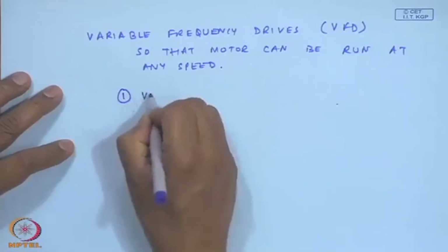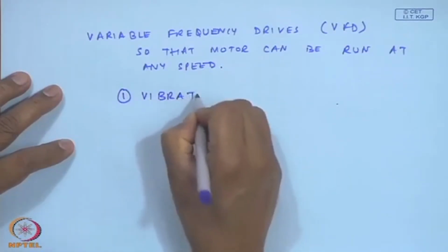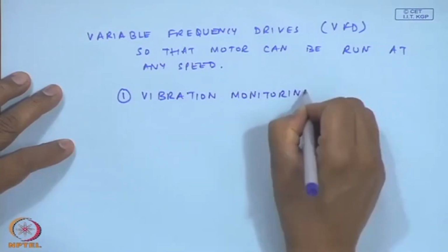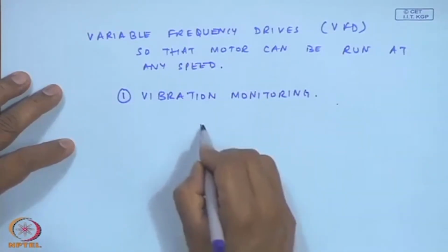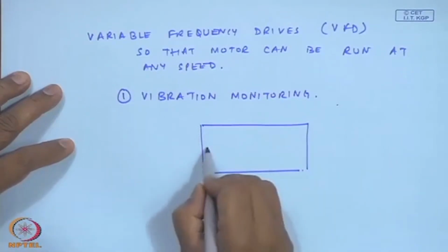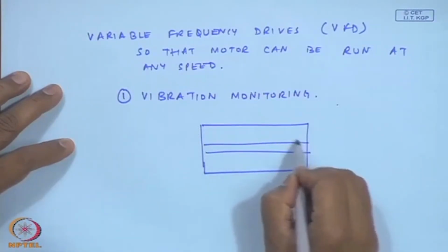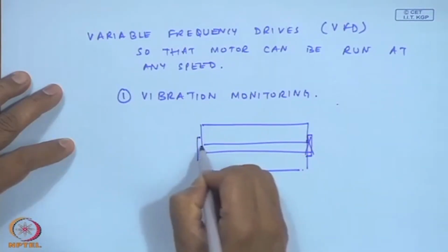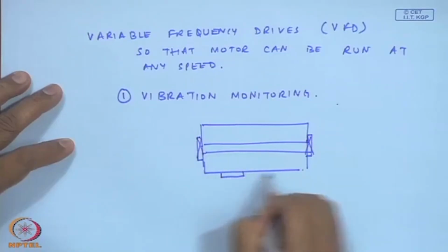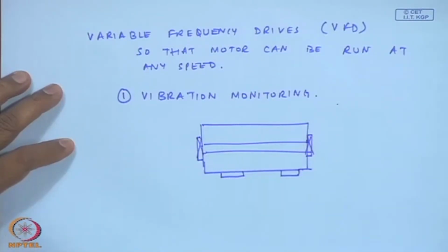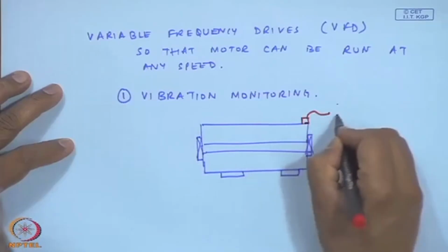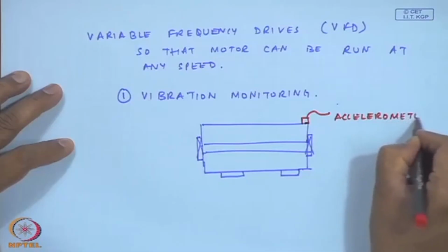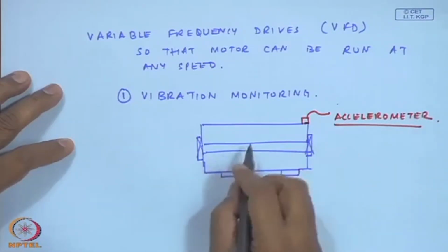And how do we find out the fault? We can still do our good old vibration monitoring on the motors. I mean, nobody has asked us not to. We can do vibration monitoring, put an accelerometer on the motor, here.